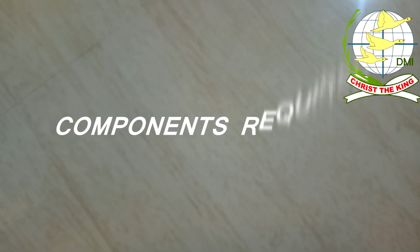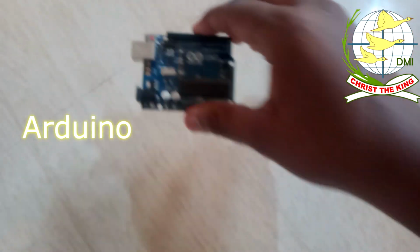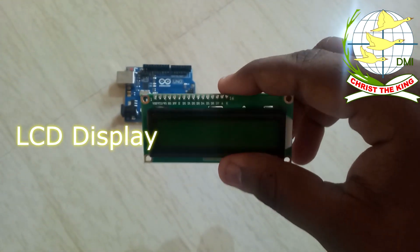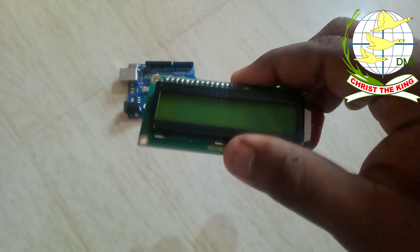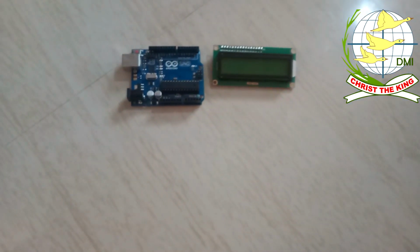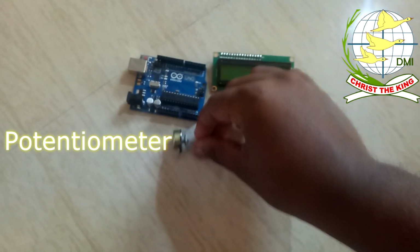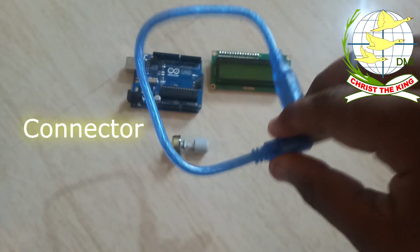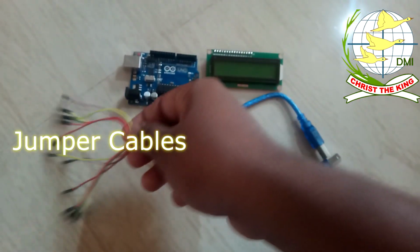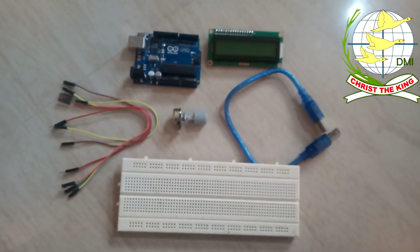Okay friends, now we can see what things are required for today's tutorial. As usual, you need your Arduino and you need your LCD display. There are two kinds of LCD display, 16x1 or 16x2. I am using a 16x2 display, a potentiometer of 10 kilo ohm, a connector, some jumper cables, and finally a breadboard. We are done with our requirements.